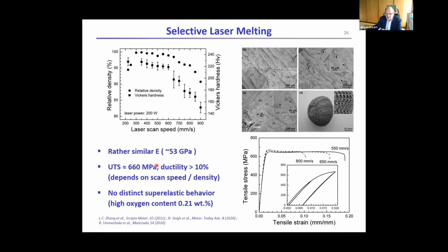So there are plenty of possibilities, and I simply don't have the time to go into the details, but adjusting the porosity, adjusting, call it the lattice structure, if you wish, can in fact really tune the properties very close to the desired performance you want for a specific patient. And since this is a relatively fast technique, if you know the parameter setting for a given alloy, this would be a way of adjusting implants on a personalized basis.